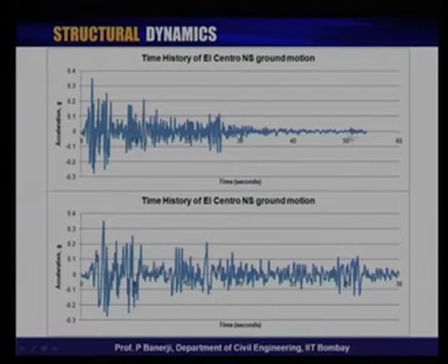Okay. So, this is how a typical ground motion looks, and this is the acceleration of the ground, as measured by an accelerometer. And if you really look at it, this is the full shaking that was seen at the station, and these parts are something that a structural engineer is not really interested in. We are really interested in the strong motion part, which is approximately about 30 seconds.